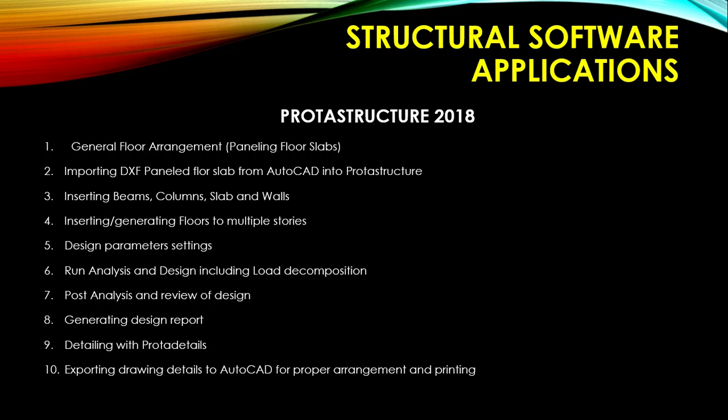You have to carefully study it so you can do a proper floor arrangement. I'm talking about the paneling of your slab and the positioning of your columns, your beams, and the rest of the things. So, number one in our Protastructure tutorial is general floor arrangement, paneling floor slabs.